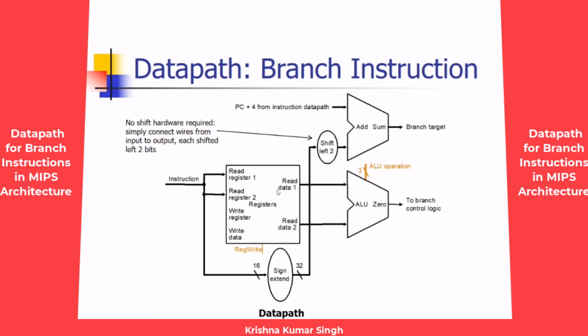So as you can see, the content of two registers will be read from the register file and given to the ALU, where we perform the subtraction operation over them. According to the zero flag, we can find out whether the content of those two registers is equal or not. And if the condition is satisfied, then the program counter should be loaded with the target address.